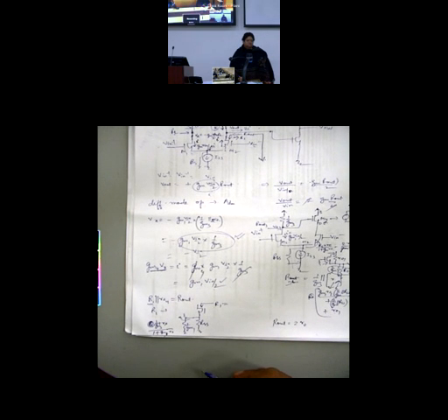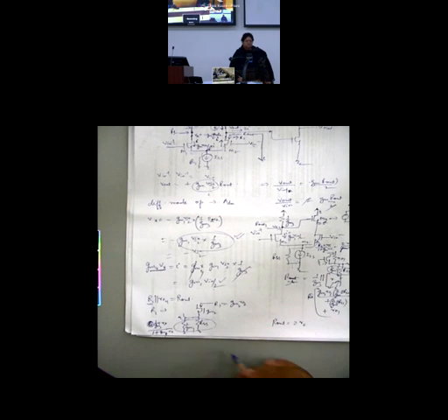So what is R1 now? Tell me. R1 will be the parallel combination of 1 by GM1 and 1 by GM1 plus RO1, RO2.